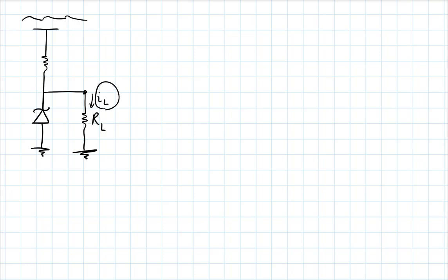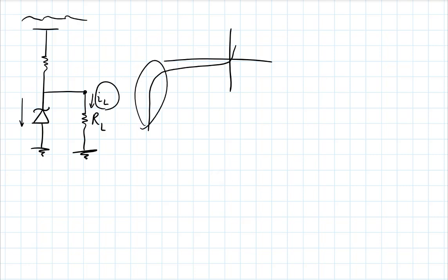the power limit, yeah. No, we're talking about the reverse. The Zener is being operated in its reverse mode, in the breakdown mode. Yes. Well, that's the point, that if this is your Zener mode, and if you greatly change the demand for IL by changing RL, you could end up either going too far here, so that's too much power, or you could end up going here, because if you require too much IL, there won't be enough left for the Zener, so you would lose the voltage regulation.